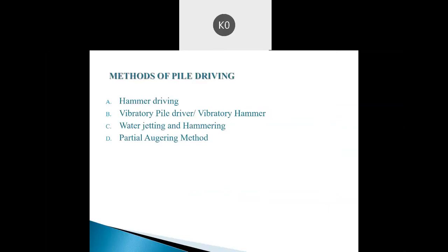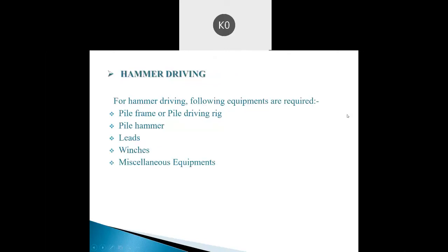Methods of pile driving: hammer driving, vibratory pile driver, vibratory hammer, water jetting and hammering, partial augering method. Hammer driving. For hammer driving, the following equipments are required: pile frame or pile driving rig, pile hammer, leads, winches, miscellaneous equipments.